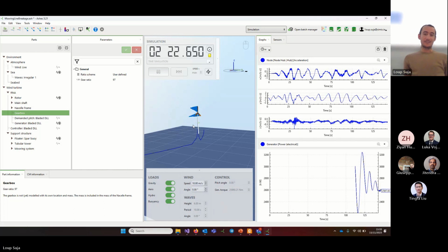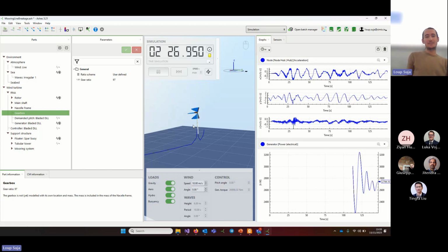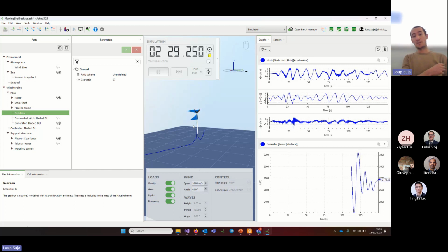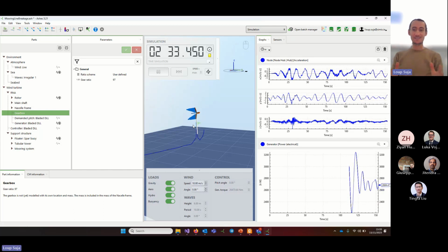But anyway, my guess is that not much actually. So you will lose a little bit of power because the wind turbine is drifting away, but that speed is really low compared to the incoming wind speed. So without having done the check, my guess is that maybe not that much. Sorry, I should have said the question for those of you online. The question was, how much has the power dropped after the mooring line broke?